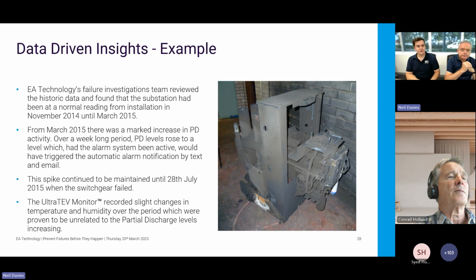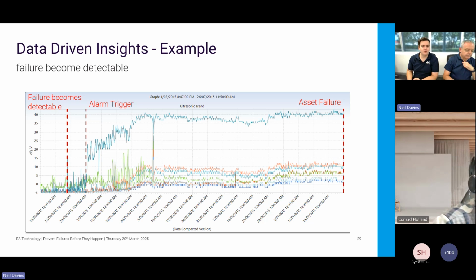Yeah. And we can see that once we actually start to look at the data. You can see when we were on site installing the monitor, everything was low level. There was nothing to detect, so you put it on. A little time later, you can see it starts to ramp up on the ultrasonic amplitudes and increase. If we relate that back to the PDF curve that Neil talked about, that is the point at which the failure becomes detectable. That is where, if you were perfect, if you were standing there, you would be able to find it at that point.